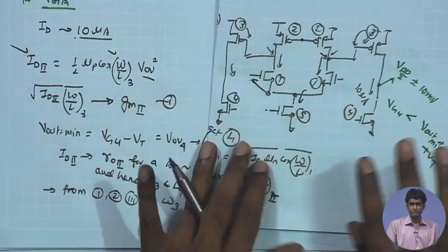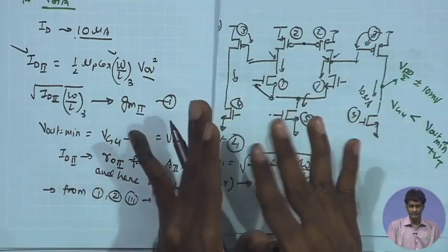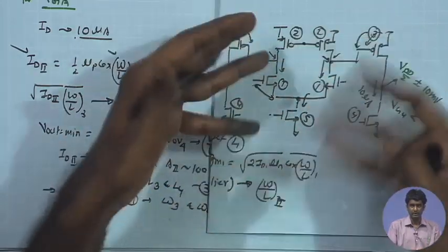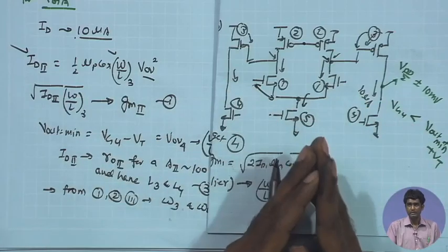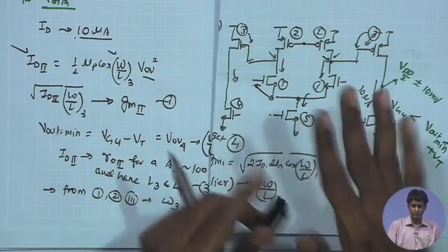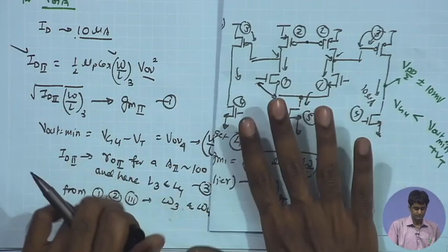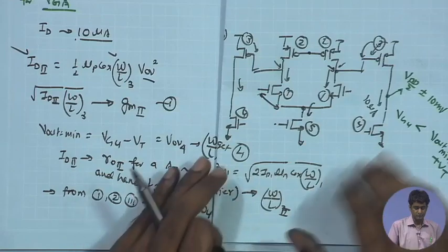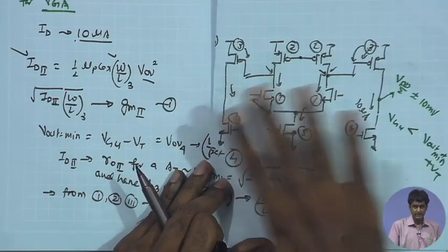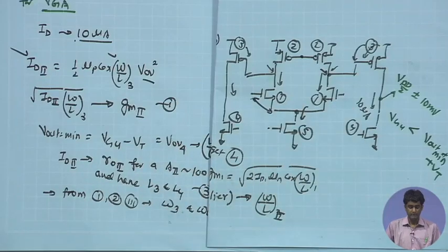So, we should just be careful about what constraint or what parameter is critical and what is not, and based on that we can determine how to size, while getting an advantage in terms of saving some bias current while not messing up any other specifications. So, I have just presented some logical steps to facilitate sizing of the front end amplifier and the second stage variable gain amplifier.